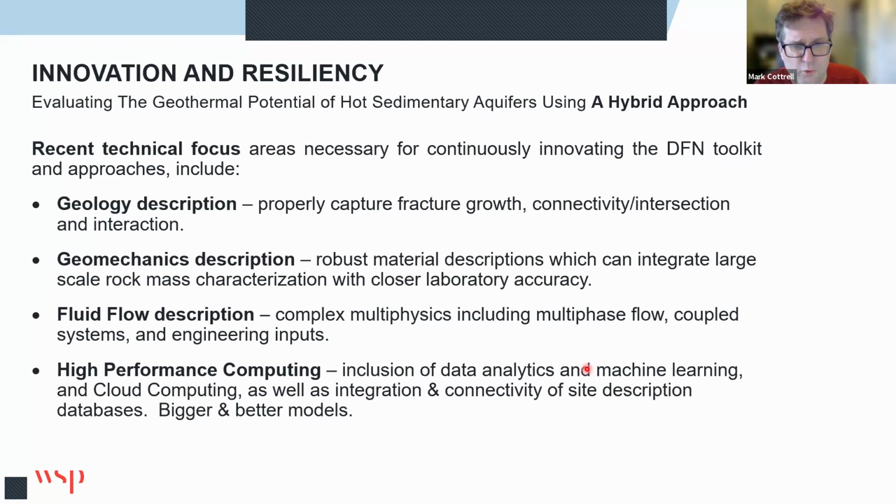Fluid flow. No longer are we in the days of simulating just single phase incompressible flow. Some of the tools out there today, and we'll see one in action today, allow us to include complex elements of multiphysics. So it's not just about simulating the fluid flow, it's about simulating temperature, the hydraulics, and also the mechanical behavior of the subsurface.